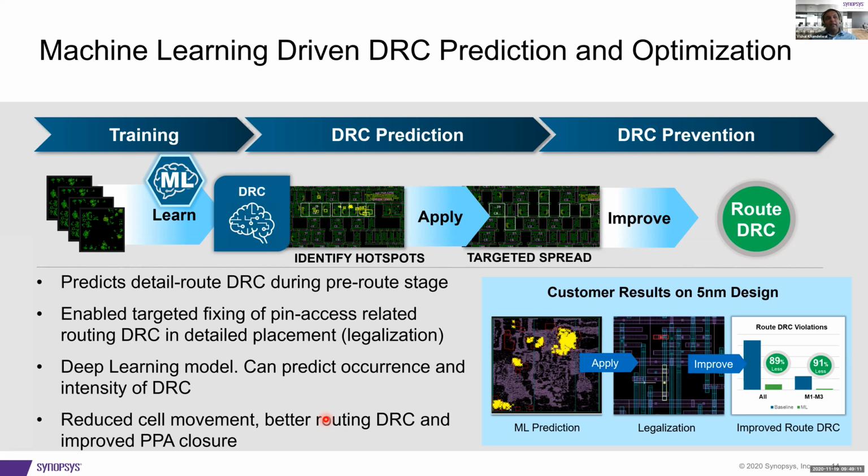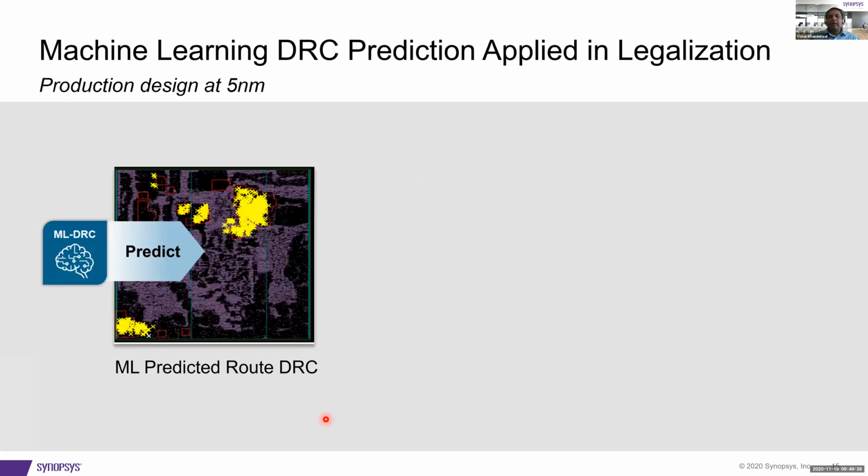And for better or worse, our global route engines are not really up to speed when it comes to modeling all of the nitty-gritty details related to pin access. That's again an opportunity for EDA researchers: how can you make global route really model all of these advanced detailed effects? So what we've done is we really integrated it in the pin access problem.